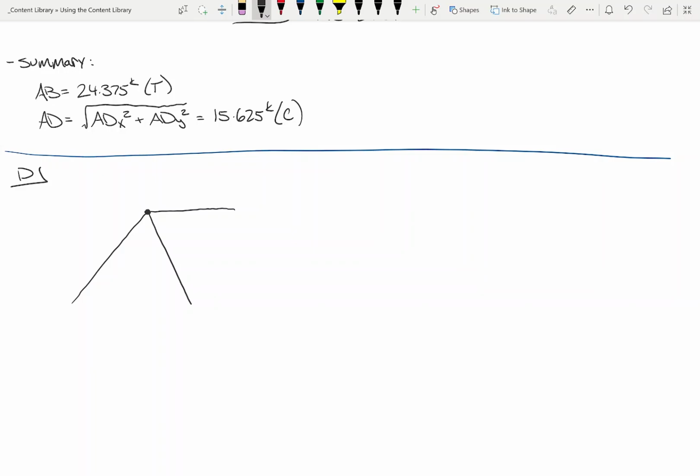Next thing that we're going to do is, if there's any diagonal members, we'll do our slope ratios. Four and three. Next thing that we're going to do is our known forces. First off, does joint D have any loads applied to it?